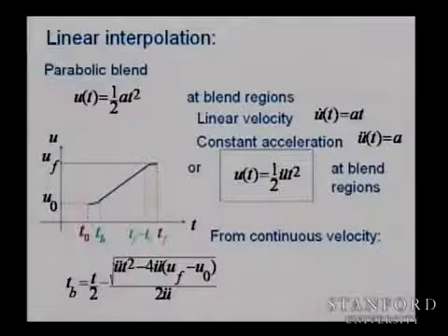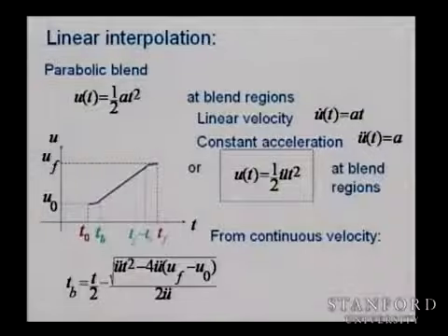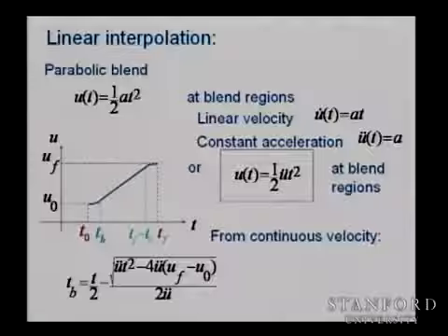So, following so far? If we want to have continuous velocity, then we can calculate the time for the blend from a condition for a continuous velocity.